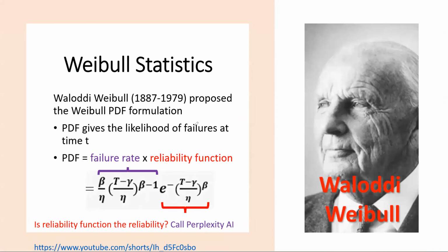It turns out Waloddi Weibull developed this. He proposed the Weibull probability density function. This is not the PDF file we're talking about; it's a shorthand for probability density function. He gave a very beautiful presentation of his formula, which has a power law and an exponential term. Later he revealed that the first portion is the failure rate, and the second portion is your reliability function.